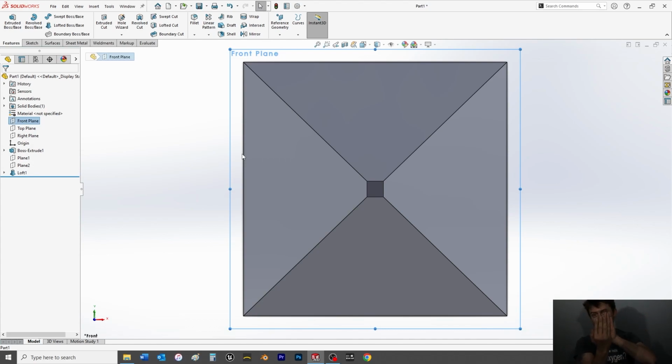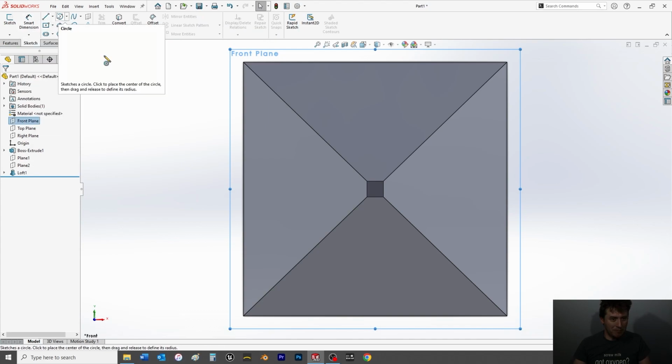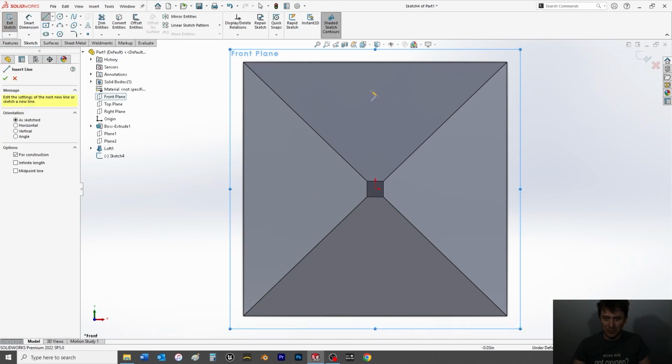But when you do this, they're lined up over each other, so now you're not really going to be able to tell the depth and what's going on. Trust the process. So now, again, make sure the front plane is selected, go to the Sketch tab, and I'm going to blaze right to a center line. And then I'm going to choose from the horizontal line, the midpoint.